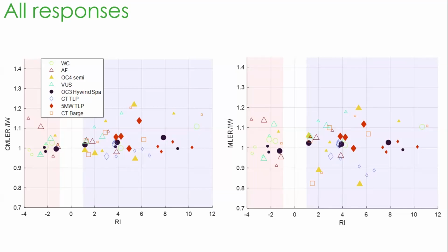It's not something I've put a huge amount of thought into. So I think there are also some limitations with the way I included some of the terms in the OpenFAST model. I was using a drag coefficient on the tower of 1, and if I'd used a smaller value of 0.5 or 0.6, it would have shifted everything to the right a bit into the more important wave region. But I think it was good to do that so that we have a wider range of cases to study.